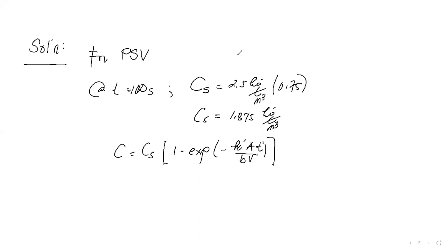This is, by the way, class, the saturation concentration. And this one is just the concentration that was achieved at 100 seconds. So this should not be labeled as C sub S, but rather only the C after 100 seconds. Because this one, the 2.5 kilogram per cubic meter, is already the constant concentration at saturation.